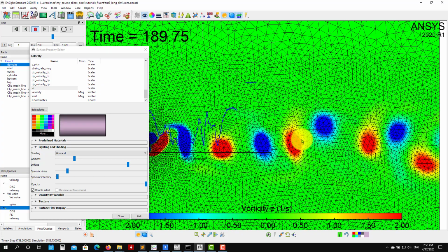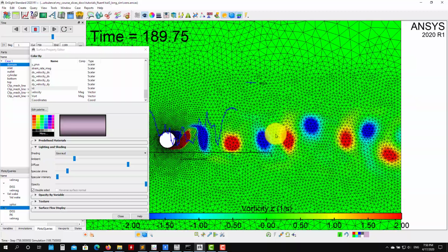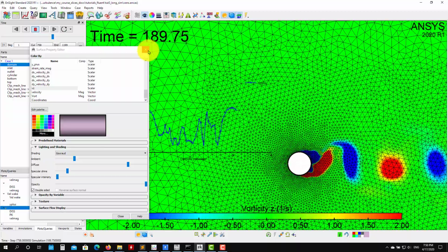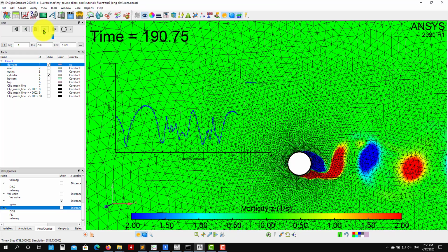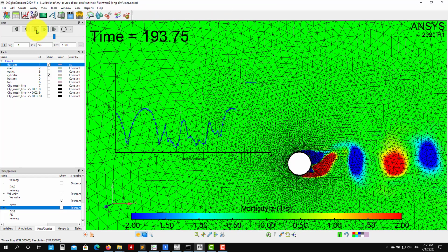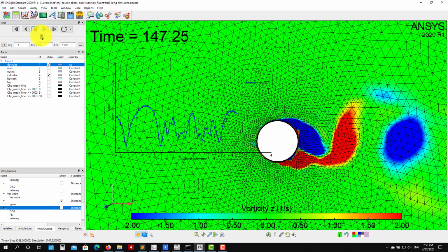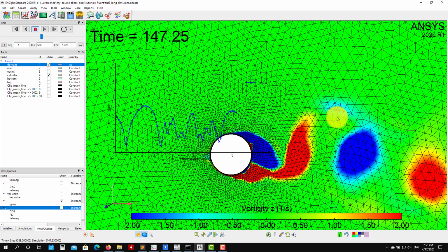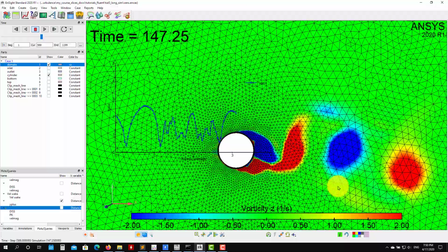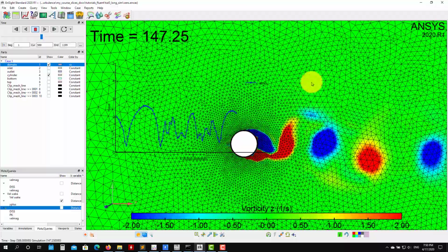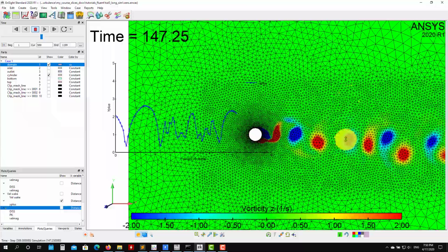To resolve large scales, okay, but remember that you might also have some small scales here. This mesh is not resolving those, but it's interesting. Let me play here and see. So see that here this comes in as a small scale, and this mesh is probably the bare minimum to resolve it. It would probably be a good idea to have an even finer mesh closer to this one in order to better resolve those vortices closer there.